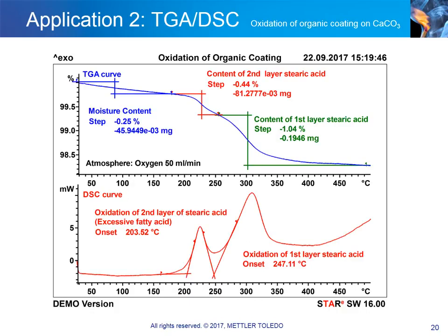Calcium carbonate is widely used as a filler in the polymer industry. Due to its hydrophilic nature, it is incompatible with some of the most common polymers, such as polyethylene and polypropylene. To ensure compatibility, calcium carbonate is frequently coated with stearic acid. Stearic acid forms a monolayered array of alkyl chains on the surface of calcium carbonate particles, oriented with the carboxylic groups adjacent to the calcium carbonate surface.